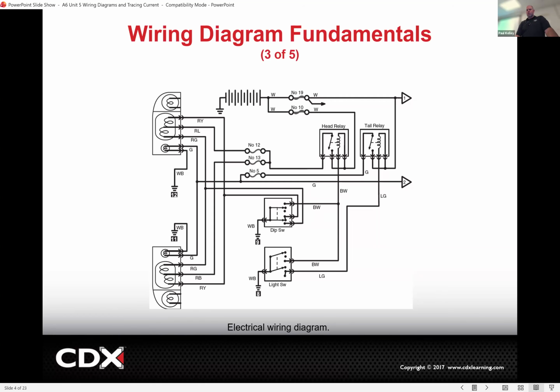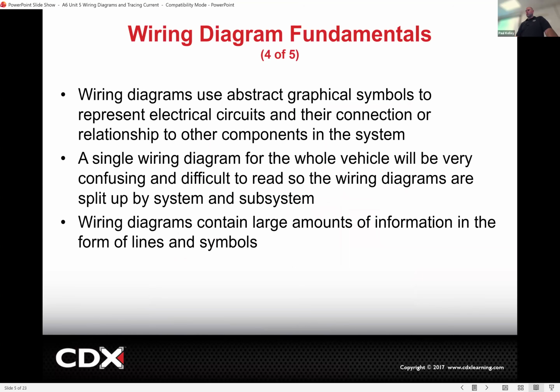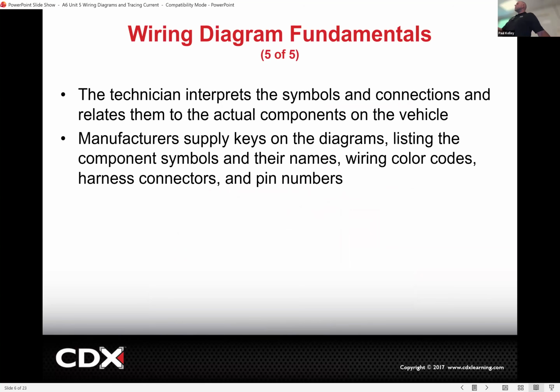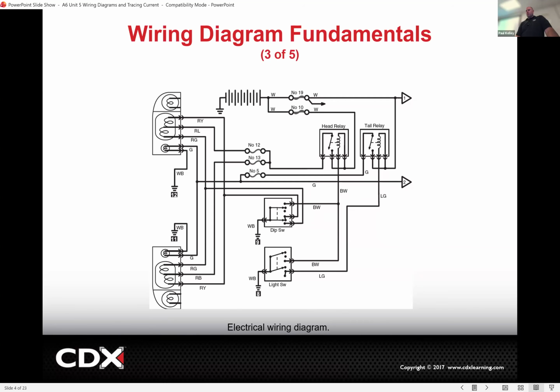But as we get further in, you'll see we also use terminal numbers, and you can track it down to where it's located in the terminal, in the connector. Cool. Any question about the colors? Go ahead. L is always light. Well, I wish. It'd be nice if there were standards that everyone followed, but unfortunately, you may see just an L, and you'd be like, "What is that?"